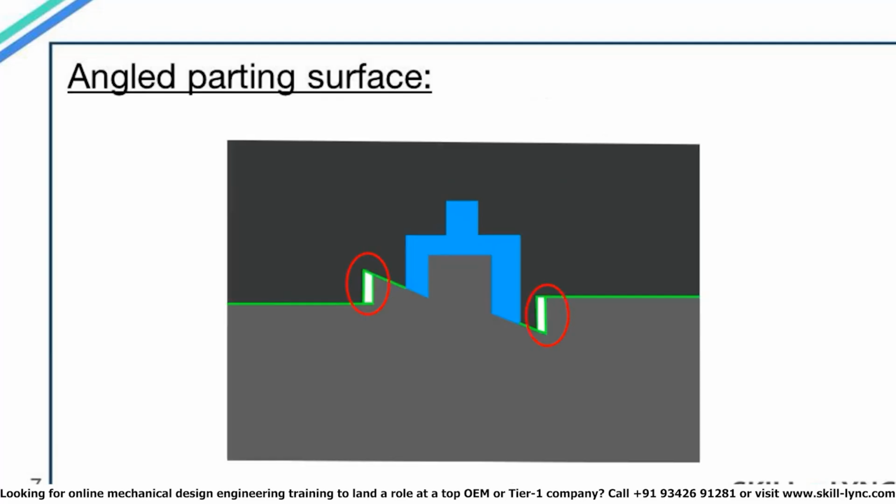And another point is, if in actual practice we were creating a mold for this component, then we would be providing some relief in the highlighted region. That basically means that the core and cavity blocks won't come into contact in this region. Now this is done in order to avoid the rubbing of the core and cavity blocks. In the rest of the parting surface, the core and the cavity blocks do come into contact, but as the core is moving away from the cavity, the blocks get instantly separated and there is no rubbing of the mold blocks.